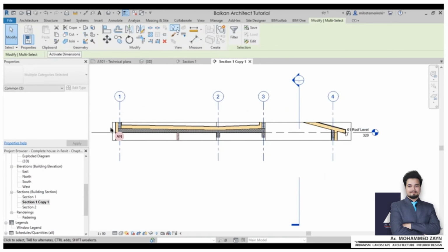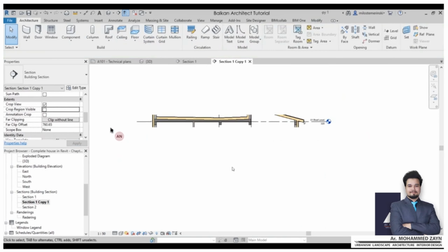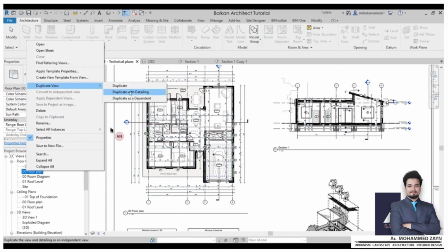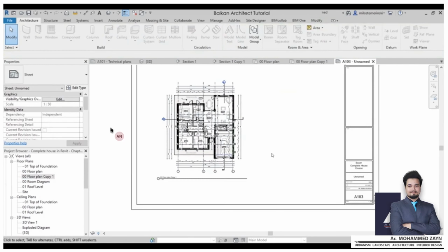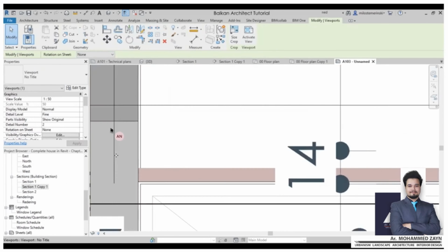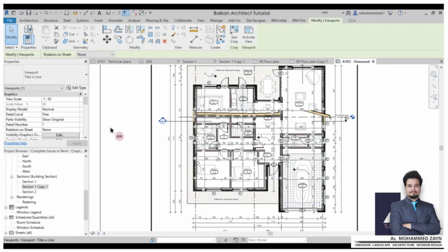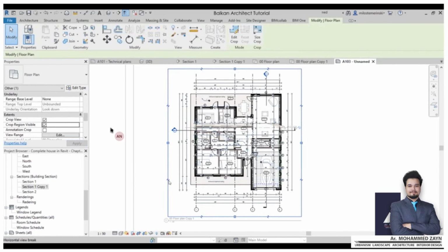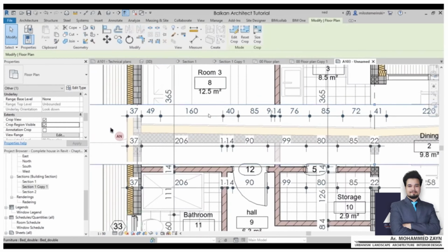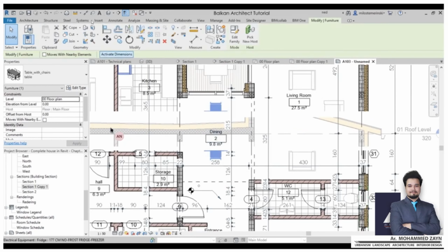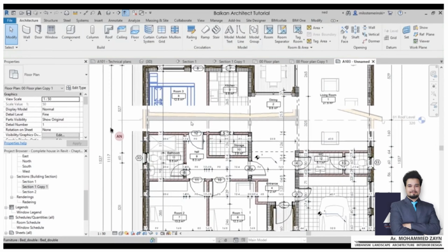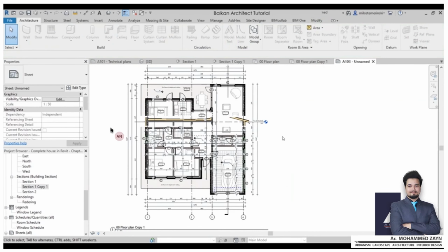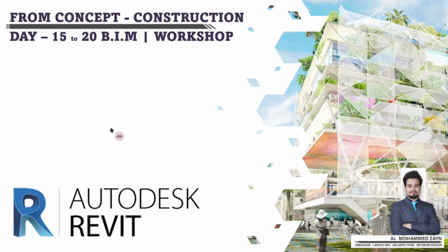In this video, you can see the creation of construction documents and setting up sheets when we are done with our drawings. Here we can see the construction details of the drawings, and how we take the callouts and details, and how we create basic sheets which are as informative and as correct as possible. So here you can see how we adjust our scale, how we adjust our far clip to show our drawings, and how we set up sheets and place our views on the sheets. Yeah, we can move forward.